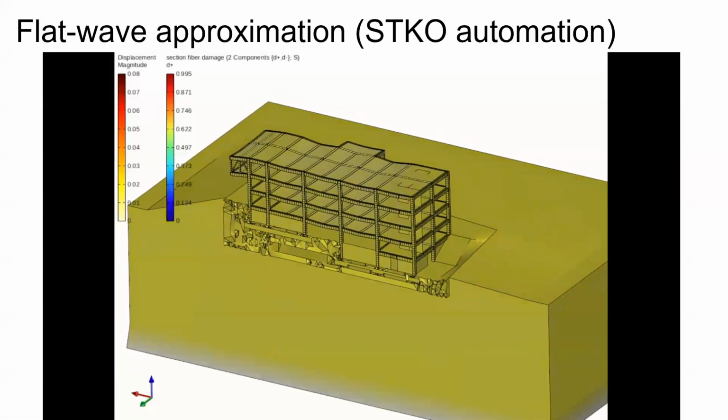Can I ask something about OpenSees SP? Yes, I can answer. I'd like to know, Massimo, OpenSees SP, I suppose it works on the basis of shared memory, same CPU, but many cores. Am I right? Is it MPI or OpenMP? It's MPI. Both SP and MP are both MPI. So you have a distributed memory, and everything occurs with MPI.